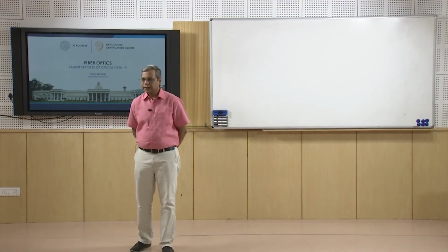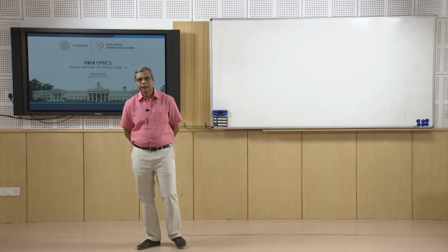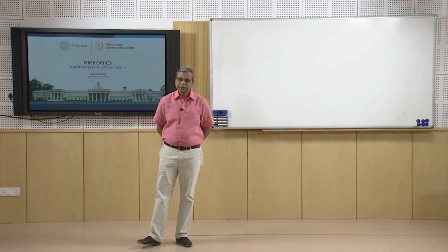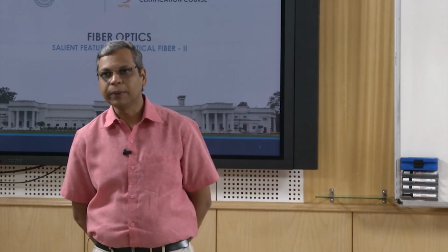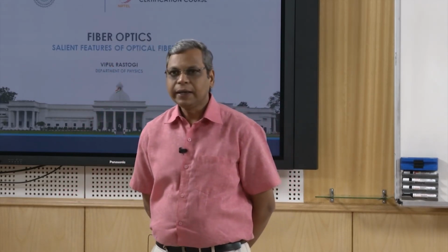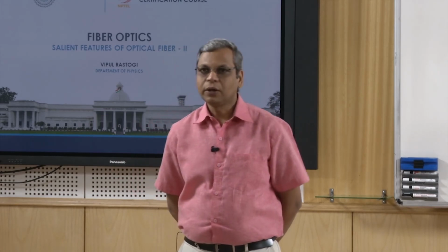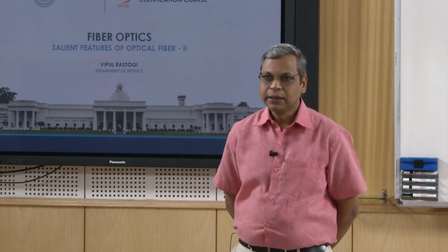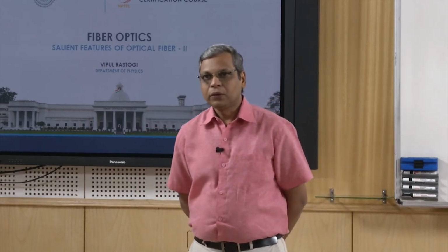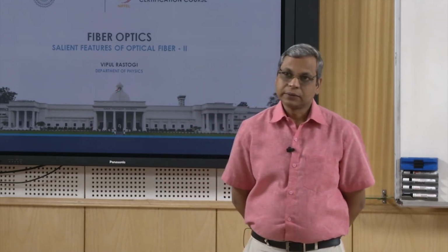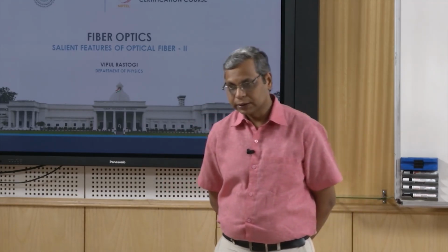But in ray theory there are certain limitations. These limitations are: number one, when we go down to the fiber core dimensions which are comparable to the wavelength of light, then ray theory does not work, it is not valid. So, if we talk about telecom fiber which has core dimensions of about 10 micron diameter, our ray theory would not work.